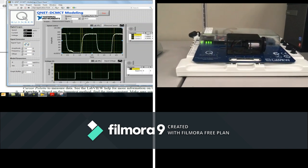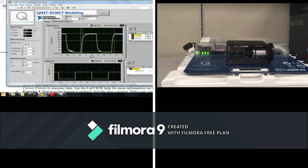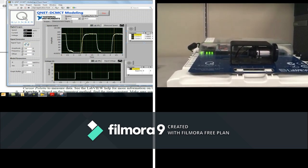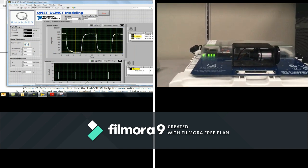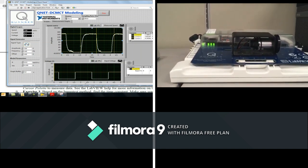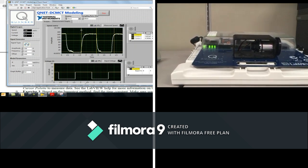That's why we have our measurement graphs. Measurement graphs have this tool, this yellow line, which I can move up and down and stop in the middle. This is cursor number 0. It shows a value of 147.32 on the y-axis. That means the highest value, the peak value, is exactly 145.536. At the same time, I have these vertical lines, for example, if I want to take this cycle, this cycle starts at this time, which is exactly, this is cursor number 0.